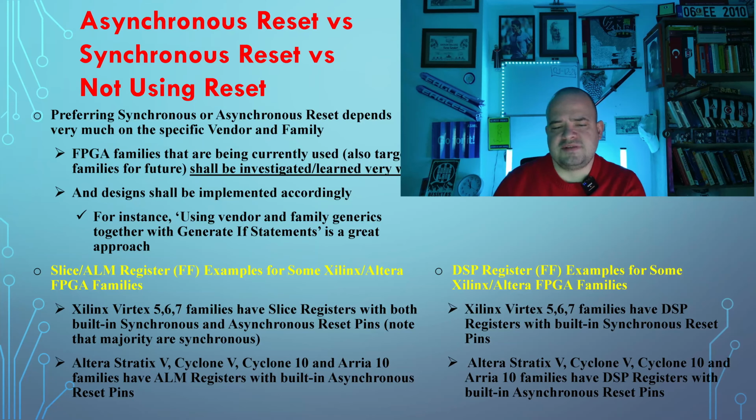Xilinx Virtex 5, 6, 7 families have slice registers with both built-in synchronous and asynchronous reset pins. But note that the majority are synchronous. Altera's Stratix 5, Cyclone 5, Cyclone 10, Arria 10 families have ALM registers with built-in asynchronous reset pins. These are for slice/ALM registers. But for DSPs, it is different. Xilinx Virtex 5, 6, 7 families have DSP registers with built-in synchronous reset pins only.